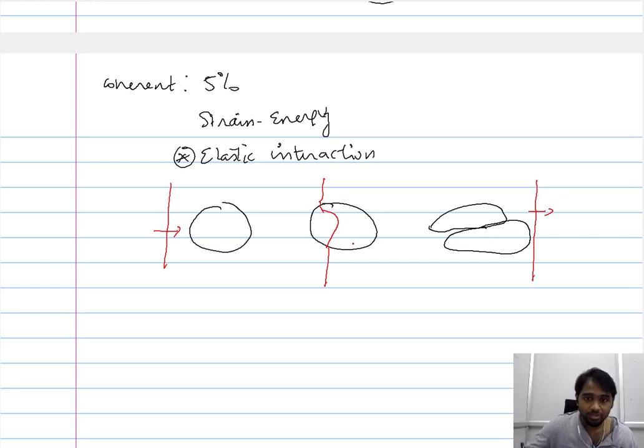So in addition to the restriction in the movement of the dislocation, or the restriction in the rate at which the dislocation moves because of this particle, what you essentially have is a considerable amount of stress being spent in the breaking of this particle, in fragmenting the particle.